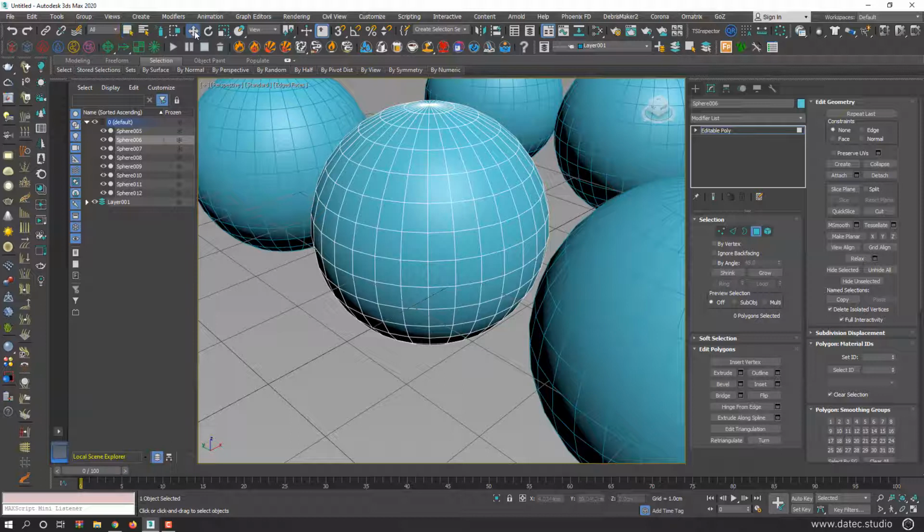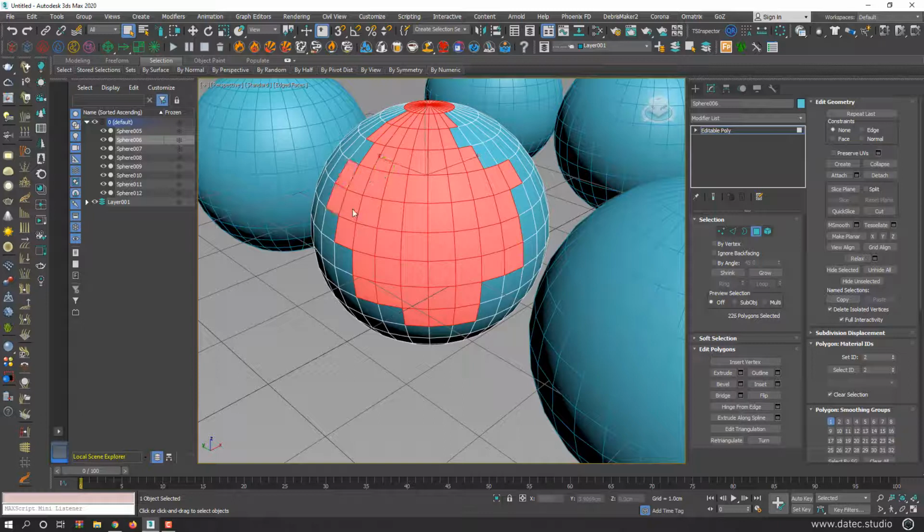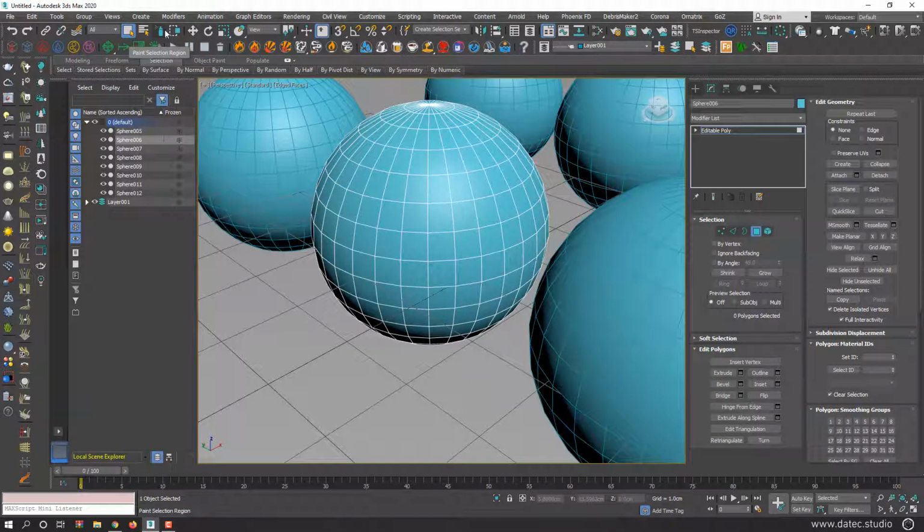If you set the Move Transform command, for example, and start dragging, as you see, your object surface will move unless you drag from the outer side. But if you enable Select Objects, you could only select them. As you see, paint region selection is very useful for easily selecting your surface. And of course, we could select other types of region.